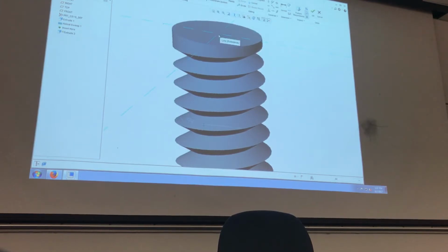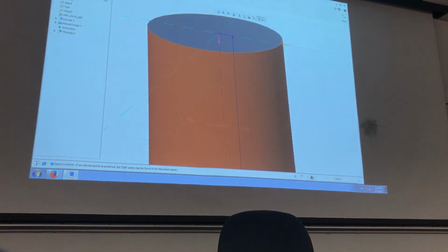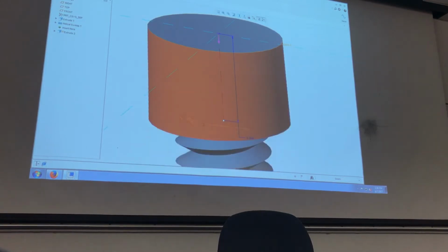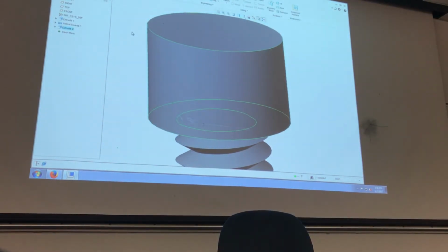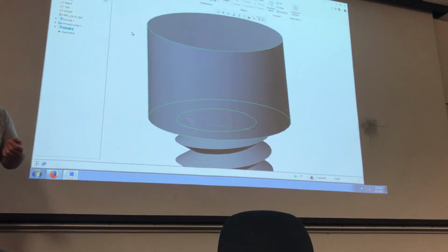Okay? So the next thing I'm going to do is extrude on top of this surface. I've got my datum turned off, but that's all right. It's going to be a circle, 0.375 in diameter. Check mark. Split my direction. And 0.244. If you look these numbers up, it'll tell you that the head will be between 0.24 and 0.244 in depth. That's why on your base plate, when we did the counter bores on the bottom of the base plate, they were 1/4 inch deep. That way the entire head would fit up inside of that hole.